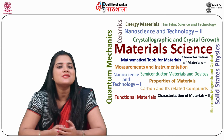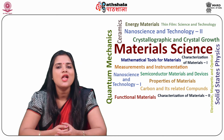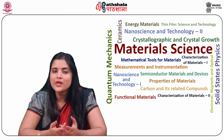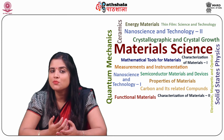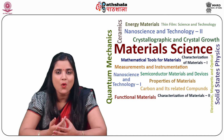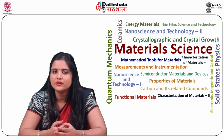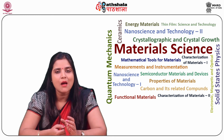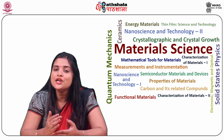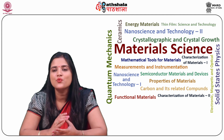Next, we will discuss the operational amplifier as voltage follower. It can be observed from equation 5 that the lowest closed loop gain that can be obtained from a non-inverting amplifier is 1 because the gain is 1 plus RF by R1. So when the non-inverting amplifier is adjusted for unity gain, it leads to an interesting application of op-amp called the voltage follower.